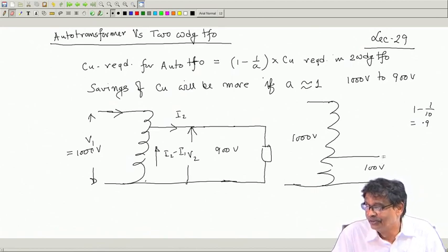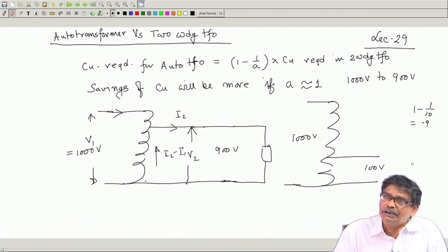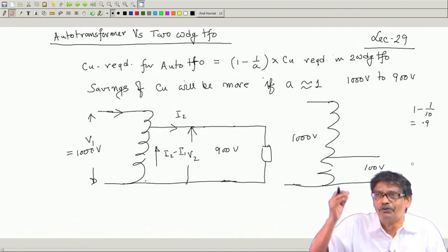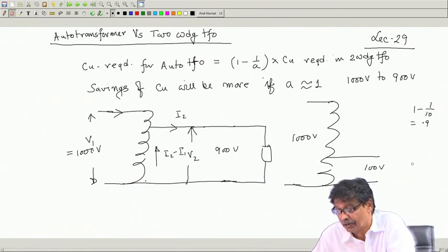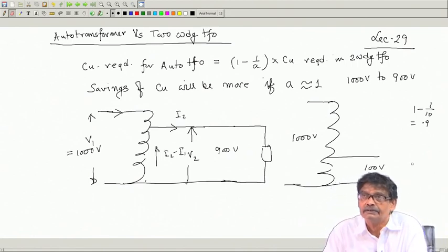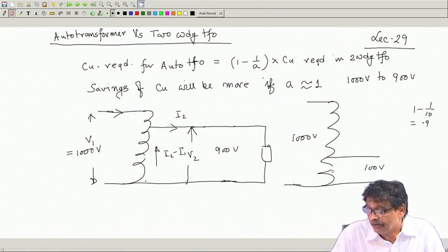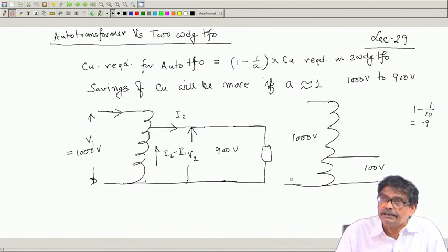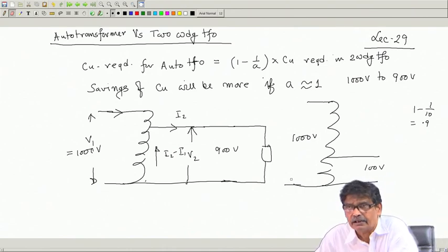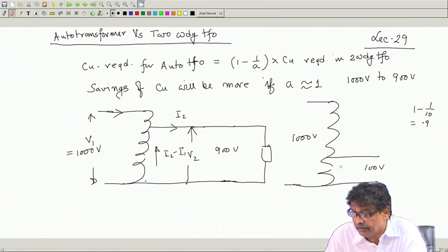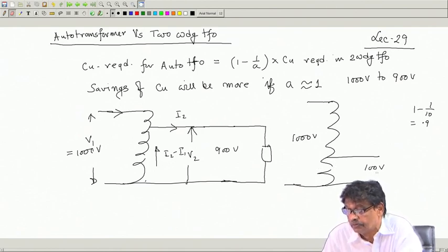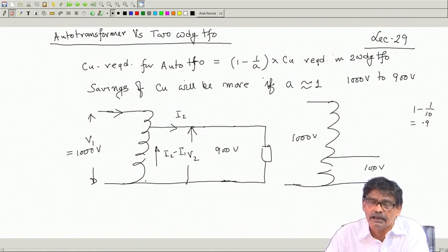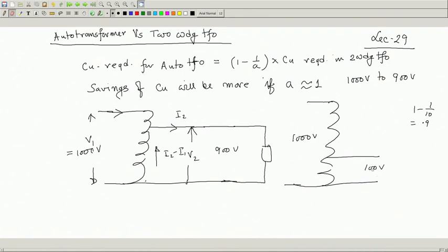But nonetheless, so far as the load on this side is concerned, it will feel that rise in voltage, or the personnel working on this side might get a shock if an open circuit takes place here, and no isolation is provided by the auto transformer. I think you have understood this point. Therefore, for the safety of the personnel who always expects 100 volt here, he will suddenly see that it has gone up to 800 volt. This is dangerous, and it may also be dangerous to the load. The load cannot accept that large voltage.